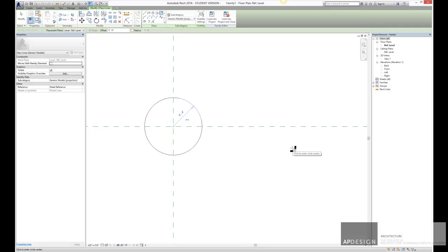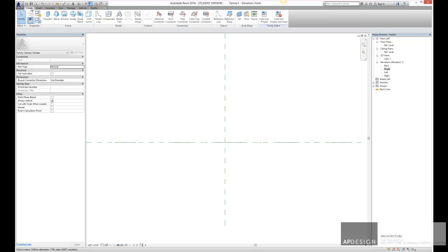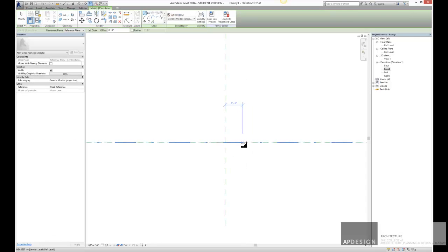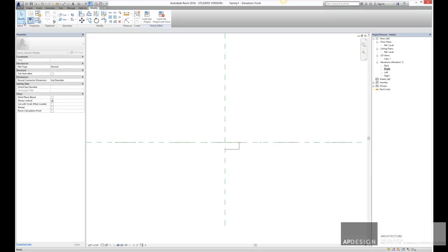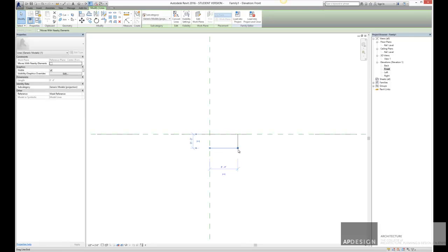And then let's go ahead and open up, so if this is a top view, or straight at the spider, coming off of this point, we'll go to front view and hit ZF to zoom in. And so that's my circle, and then I'm going to draw a couple other modeling lines coming from that circle down, say 2 inches, and then over. So that gives me a rough framework of this is the center of the spider, and it'll come up to that point. In fact, it might be a little bit more visual if you do it like that.